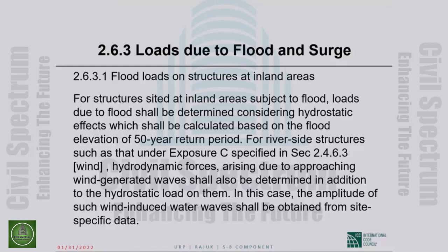For riverside structures such as under exposure C, that is wind exposure C, which we'll discuss tomorrow, hydrodynamic forces, not just hydrostatic, arising due to approaching wind-generated waves shall also be determined in addition to the hydrostatic load on them.